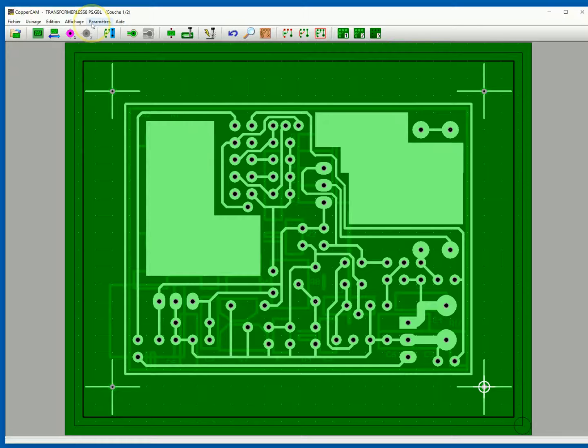I take the board and plunge it into acid, and after some time, all the space between the black paint, the copper will be removed. It's easier and faster than milling mechanically like almost other people do. To do a standard size PCB, maybe 6x6, milling could take 4 hours, something like that. But with the laser, it took about 20 minutes, and the result is better than the milling, and you will never break a bit.